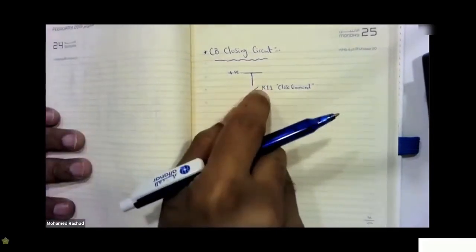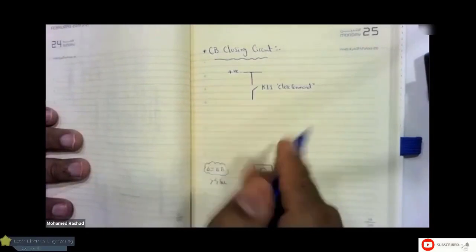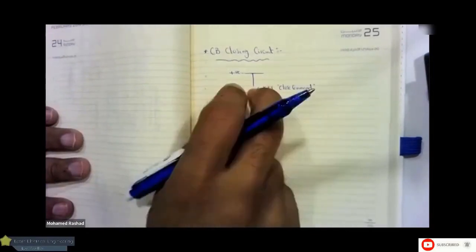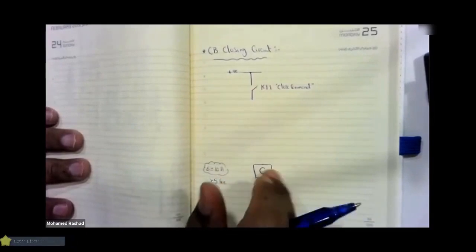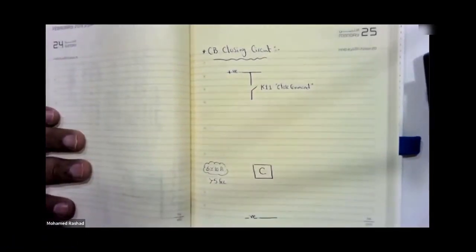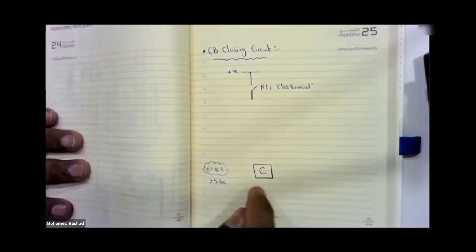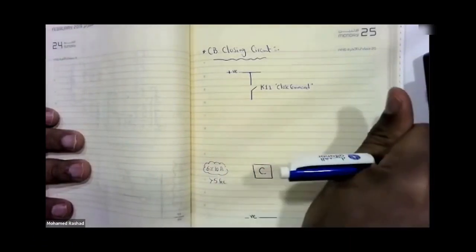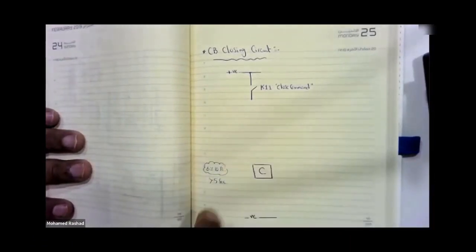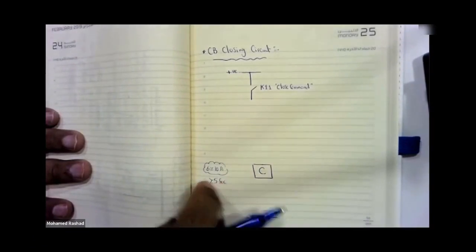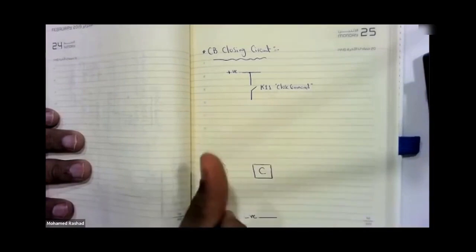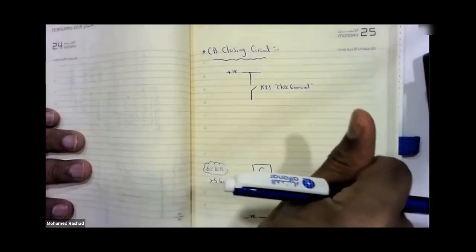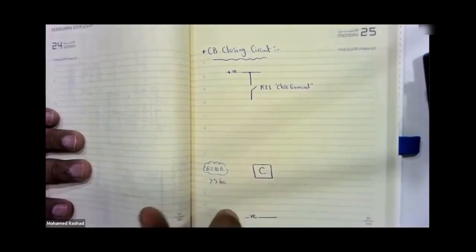All right, if you are playing around and keep pressing, and an operator who is not paying attention keeps giving the command to close, close, close, close, while the breaker is actually closed, will the breaker close? No, the breaker will not close, right? It's a mistake by the operator, since it is already closed. But this action will cause the coil to draw the current I mentioned. He should press properly, hold his hand for 2 seconds, and then remove it. Naturally, if he keeps pressing and releasing at close intervals, pressing for a second or two, you'll find that your closing coil is burned.